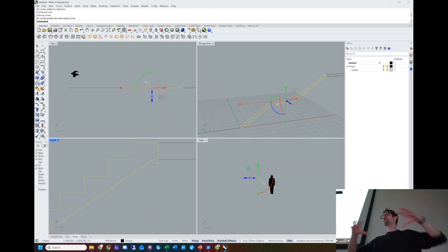And that means it's not watertight, it's not a solid, it's not going to end up being a single solid piece of geometry. It's going to have a big hole in it because the lines haven't been joined up. But because I have joined them up, and I've made sure that they're closed, it's a closed loop, it goes all the way around and keeps going.